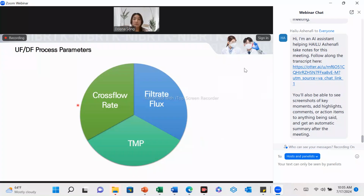So when performing ultrafiltration and diafiltration, there are important parameters: cross-flow rate, filtrate flux, and transmembrane pressure, TMP. These three parameters need to be well controlled for the UFDF process to work effectively. By understanding and controlling these parameters, we can ensure a successful UFDF process. So let's take a closer look at each one.